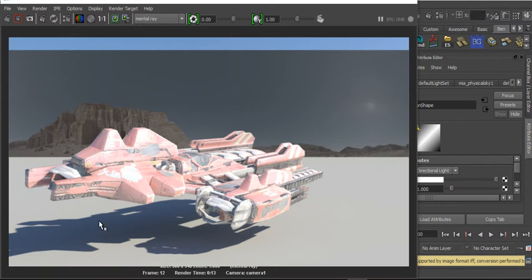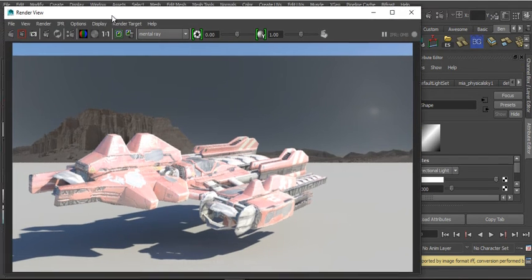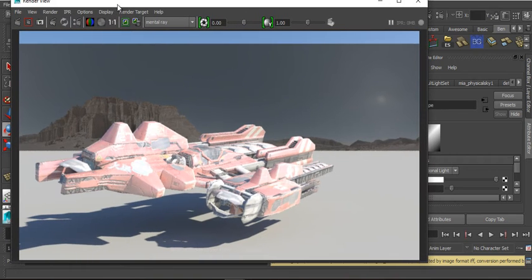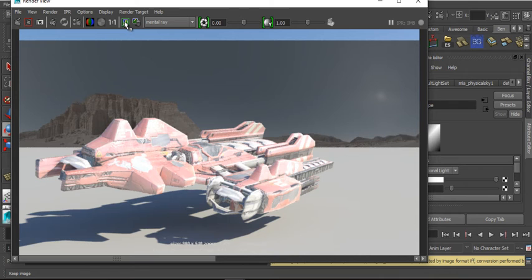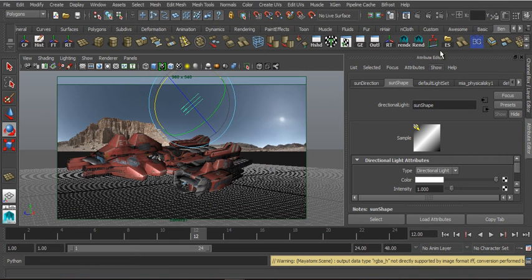There's going to be a few test renders that we're going to do as we gradually improve what we're looking at. It's important to keep any previous images so that we can see the improvements. Every time we hit render, this will be replaced unless we hit this keep image button. This doesn't save it onto your computer, it just keeps it in your computer's memory, and you can drag through it by scrolling down here. So make sure you click on keep image. You can close your render view for now, and then we can see what settings we can change to improve that.